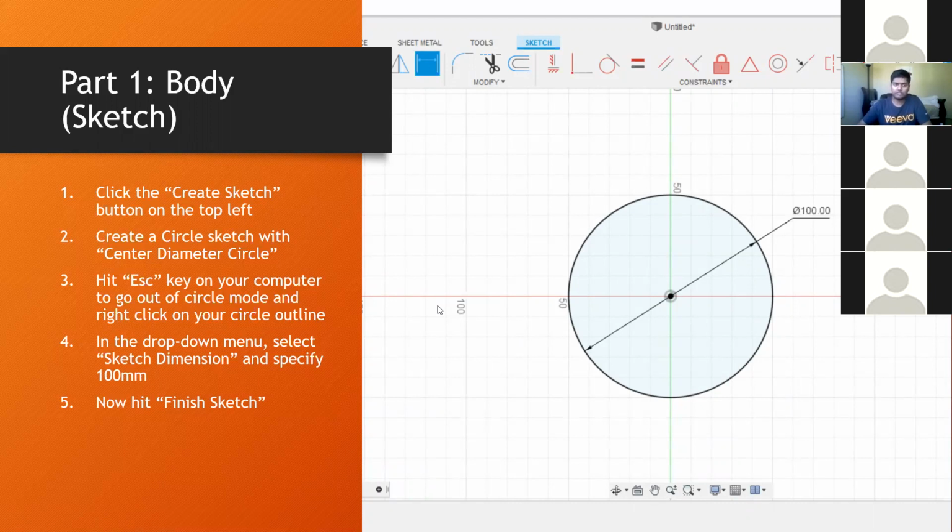And the reason is because I'm going to modify this later right now with the sketch dimension tool. And this is similar to coding syntax. You don't have to use the sketch dimension tool, but it helps you with editing later on in case you want to change the size of the bottle or whatever. So we're going to use the sketch dimension tool here. And we're going to click this. And now we're going to specify 100 millimeters, which is roughly the diameter of a hydro flask. So use your mouse to scroll in, and there you go.